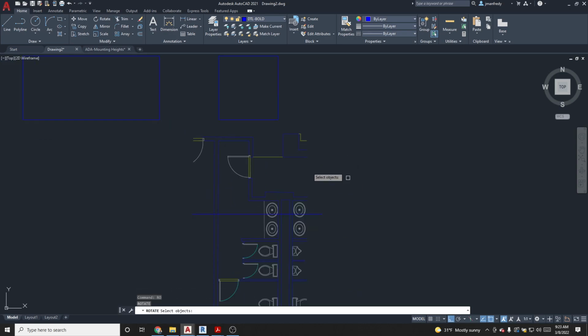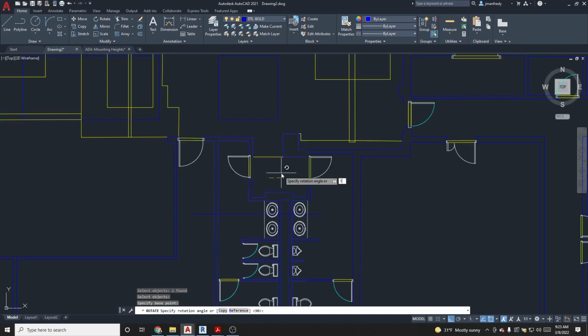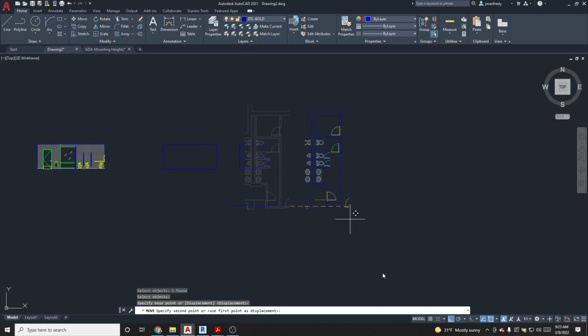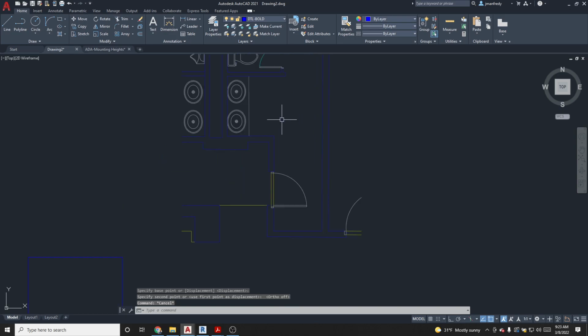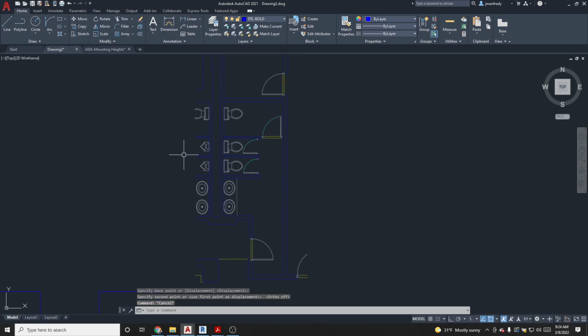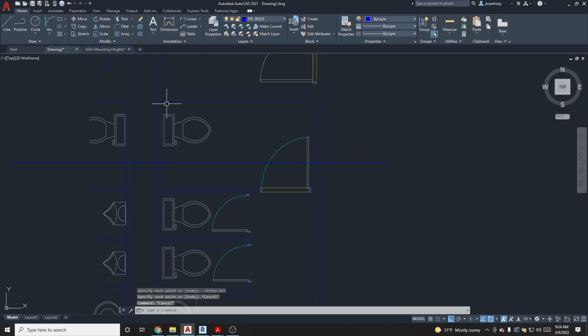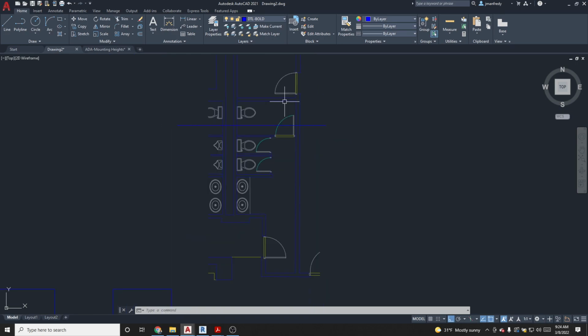And then you can rotate this a second time, or a final time, 180 degrees. And move this drawing out of the way. Turn off ortho. And where I'm going to stand, I'm going to stand in this back room here. And I'm going to draw this wall. What's on this wall and what are the fixtures along that wall there? Standing on this line here, I'm going to draw that room, that elevation right there. And I'm going to draw it right here.